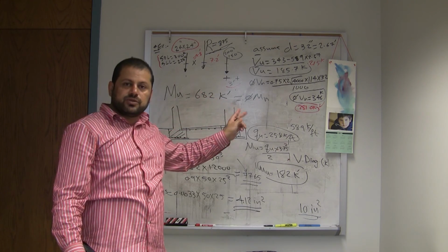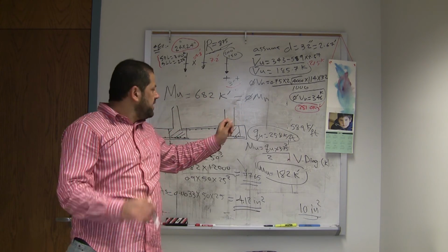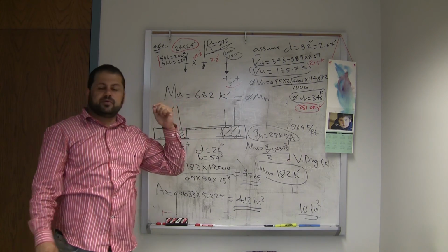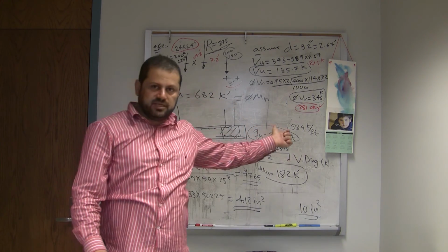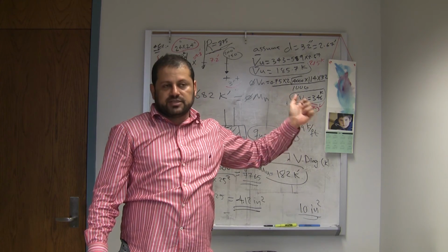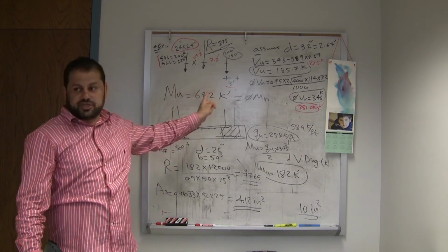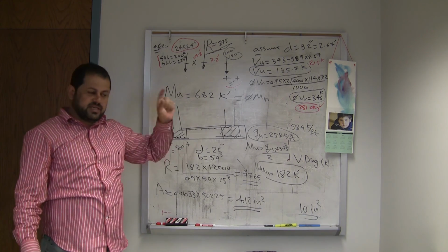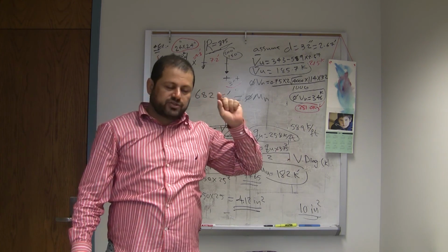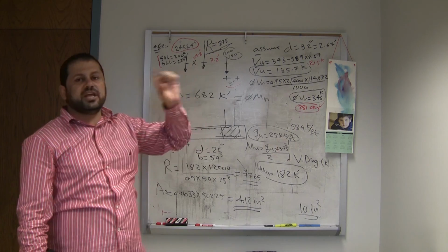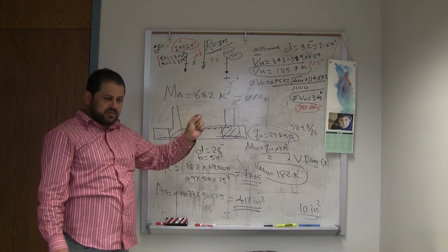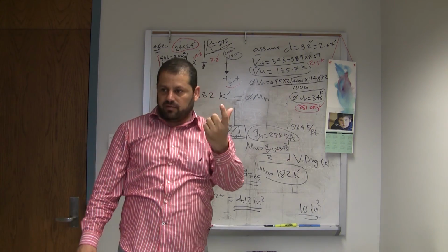If you calculate per foot, how much you need per foot, it's going to be 0.002 times D, which is 26 inch, times H, which is 30 inch. Rho minimum, AS calculated for shrinkage and temperature, is multiplied by BH in footings and in slabs. So you do 0.002 times 30 times 12.